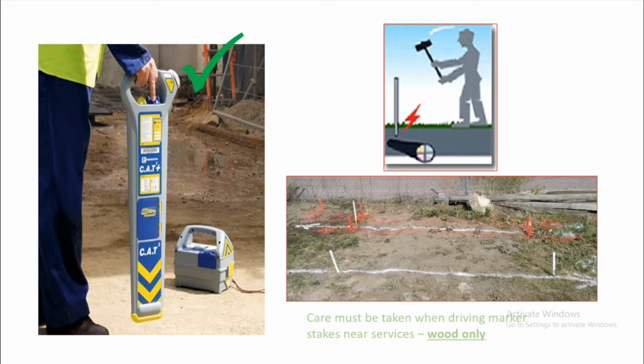So the issue is when they scanned it, they knew that the cable was going in one direction only, but they didn't know that the cable was previously looped at that location. They made a roll and buried the cable at that location. So they hit some part of the energized cable with 5 kilovolts, and immediately it gave an explosion to the equipment.